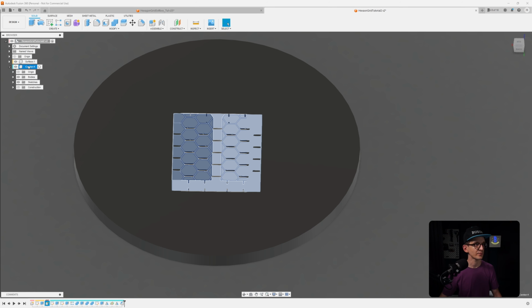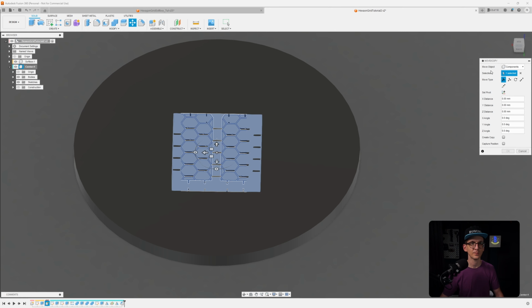And what we actually want to do is not to copy it with the move and copy tool, because this will create a copy that will be referenced exactly the same. And when we change one of those copies, all of them will be changed, which is not something we want. We want now to create the basic shape on the edges and the corner piece. What I mean by that is, maybe I do it.